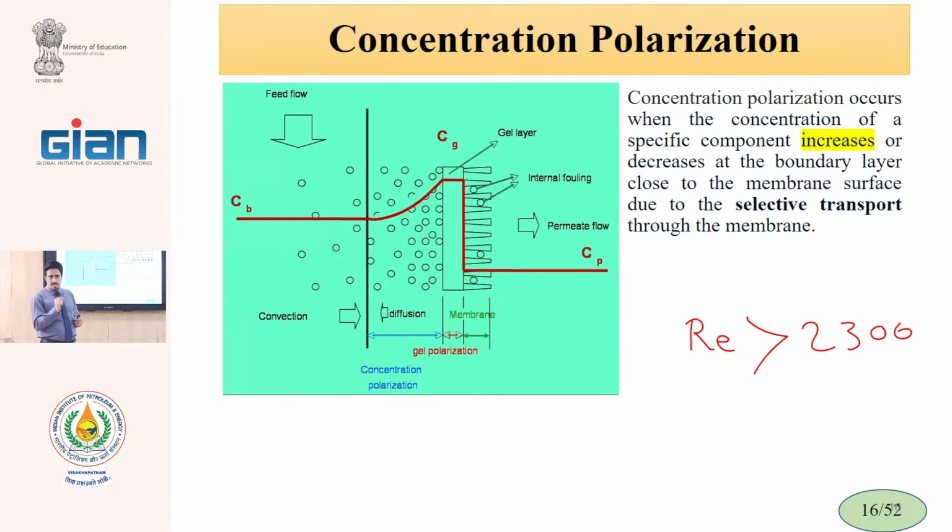Feed speed is very important in the spiral wound, and when we want to buy a module, one of the parameters in the brochure of the membranes is the feed entrance speed. The higher the feed speed, the bigger the Reynolds number.